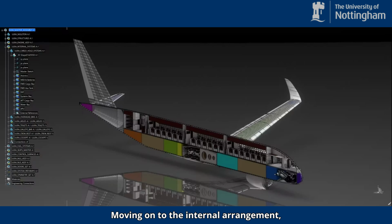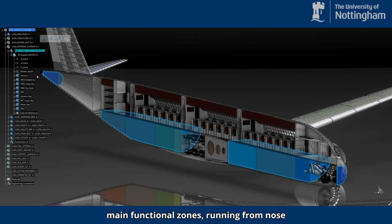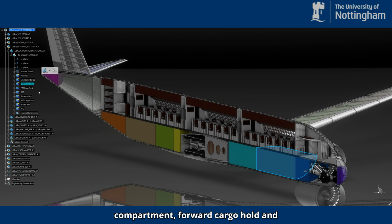Moving on to the internal arrangement, this section shows how the main internal spaces were allocated and represented within the CAD model. The clearest way to show this is through the aircraft cross-section. Under the cabin floor, the fuselage was divided into a series of main functional zones, running from nose to tail. This includes the avionics compartment, nose landing gear bay, battery compartment, forward cargo hold, and forward auxiliary tank.